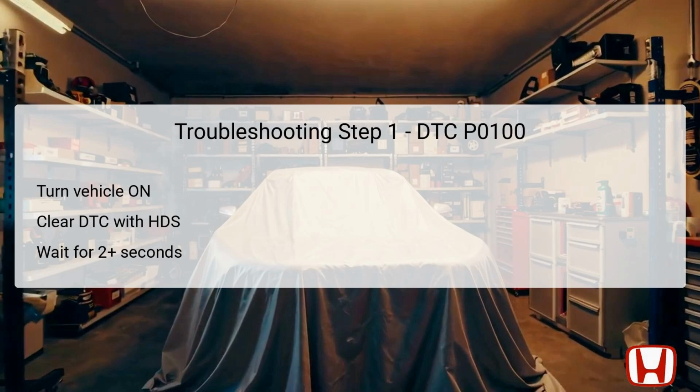In the first step of troubleshooting for DTC P0100, start by turning the ignition switch to the on position without starting the engine. This action allows the vehicle's systems to enter a diagnostic state and prepares them for monitoring. Next, utilize the Honda Diagnostic System, HDS, to clear the diagnostic trouble code from the system memory, which resets the error status. After this, it is crucial to wait for 2 seconds or more to give the onboard systems adequate time to reset and recalibrate.